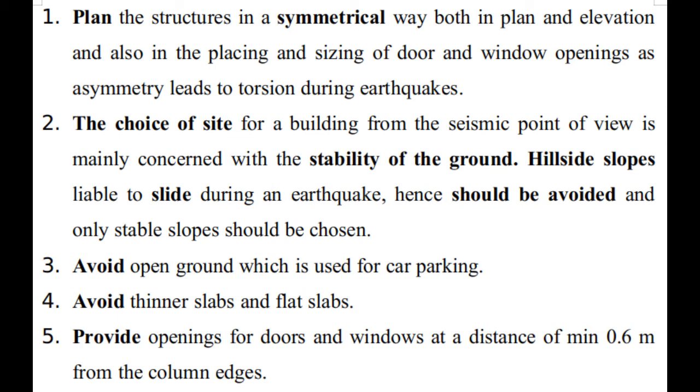Second point, choice of site. While choosing the site of the structure, we should be very careful from the seismic point of view with respect to the stability of the ground. Remember that the hillside slopes are liable to slide during an earthquake, so it should be avoided, and we should consider only the stable slope for the construction.